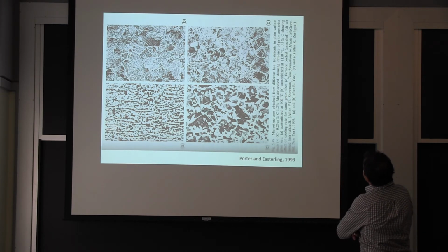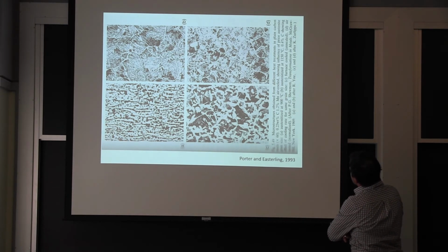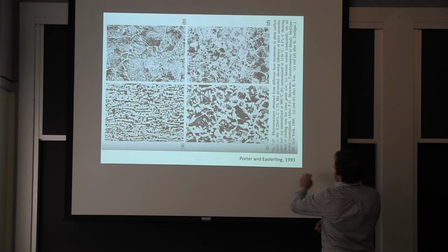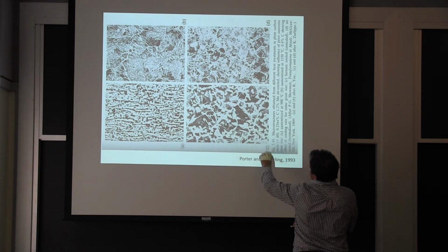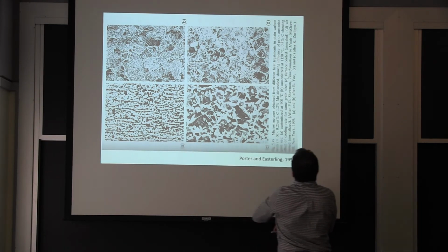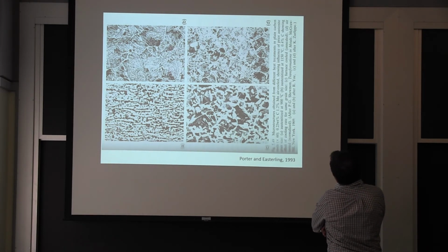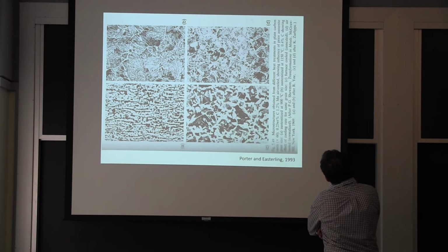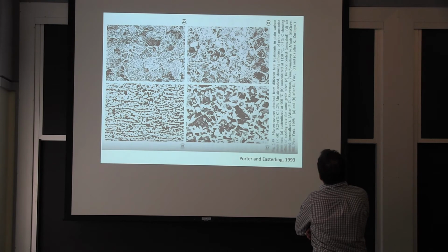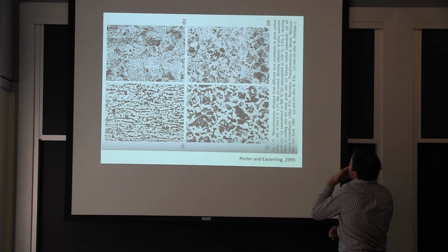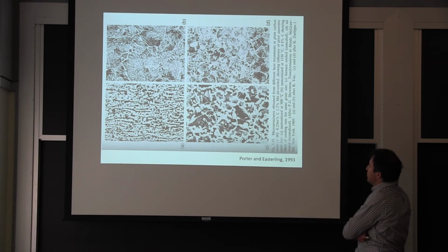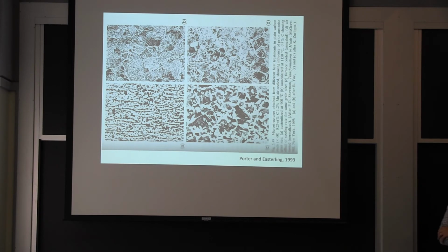Furnace cool anneal. So this is coarser than this one, for example. So if I go to A, yeah, it's cooled normally. Normalized, it's air cooled, and the furnace cool gives you a much coarser microstructure, much bigger grains.